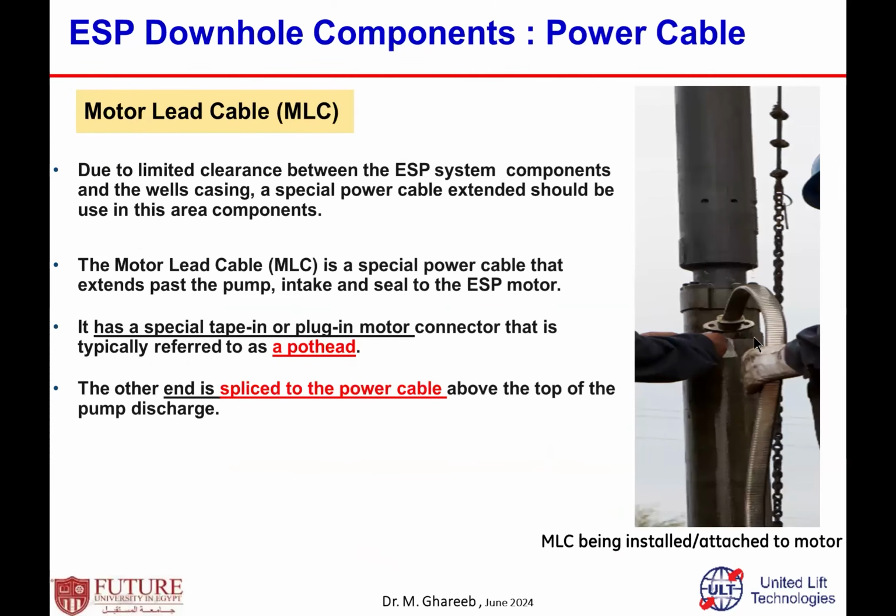At the motor itself, how are we connecting this cable to the motor? There is what we call the motor lead cable. Due to the limited clearance between the ESP system components, the motors and all the bottom hole assembly components, and the small clearance between this assembly and the well casing, a special cable can be extended downhole around this bottom hole assembly.